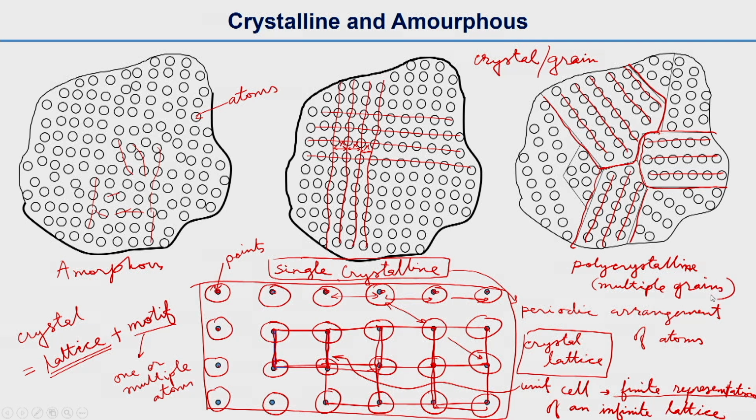And as you know, most metallic materials are polycrystalline, because these grains are on the order of micrometers, like 10 micrometers to 100 micrometers, but sometimes you can make very big grains, like for turbine blades you can make single crystal turbine blades. Engineers are now so expert that they can make even very big grains in centimeters or meters, and they can also make very small grains at the nanometer level. That is called nanocrystalline material. From nanometer to probably meter you can make grains, depending on your expertise in metallurgy and materials engineering.